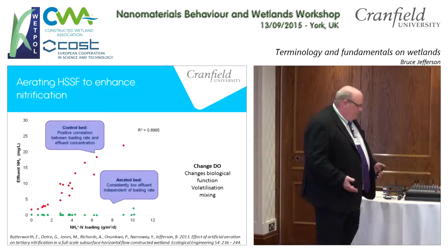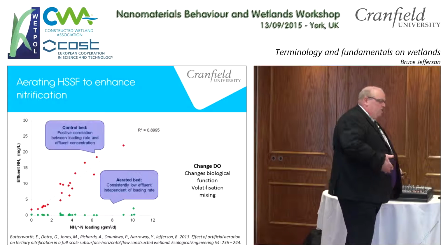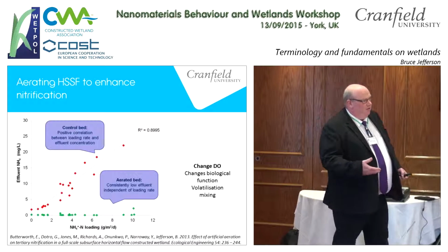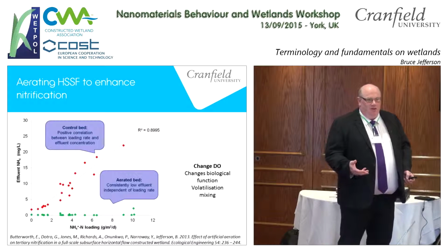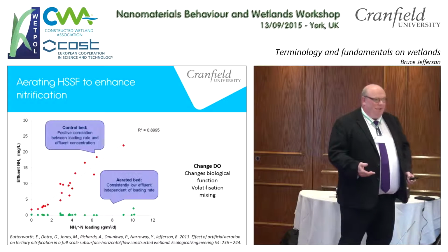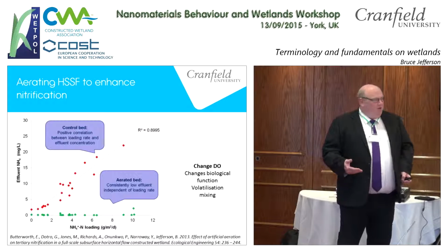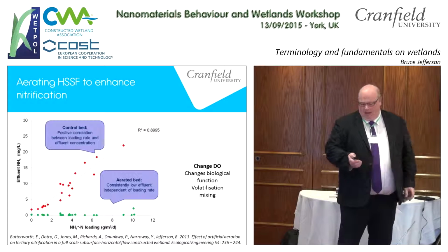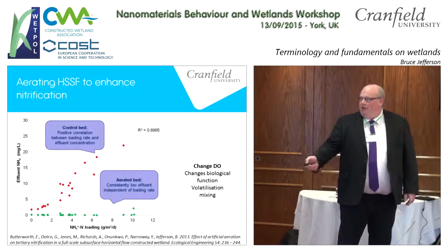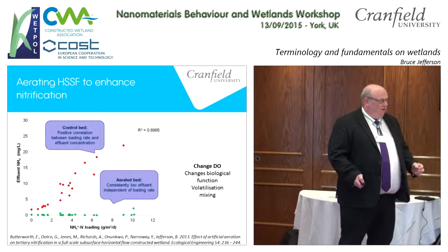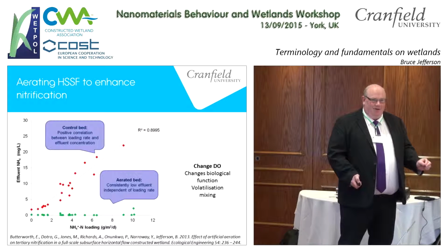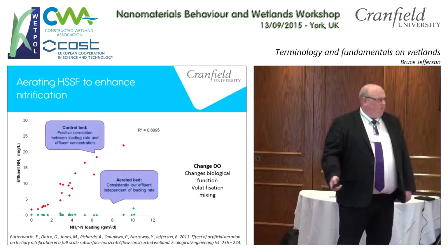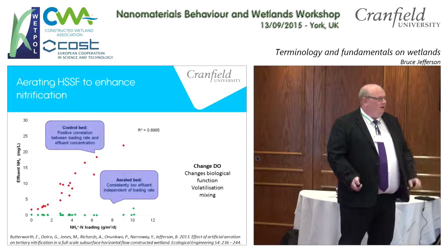And then what's happening? So we're starting to need to remove ammonia in these beds that were there for solids. So one of the big things that's been happening is people are starting to add air. So a little bit of aeration completely changes the function of the bed. So I've got my traditional one here. I can only get to low ammonias if I treat it at very, very low loading rates. I add a modest amount of air, and actually it completely nitrifies.